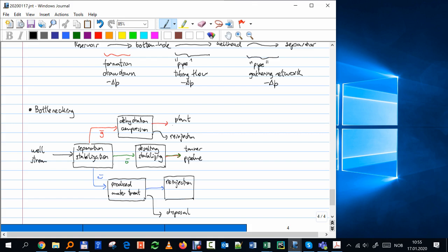Simply by separation, I mean it's like a multi-stage of separators. That's what you typically have. But after that, the crude still needs dehydration. It has significant amounts of water that you have to remove, and might have salt. You don't want corrosion because of water and salt. They can cause corrosion in the tanker, in the refinery, many things. And also stabilization, because that oil, if you put it in a tanker at atmospheric pressure, will still be able to liberate some gas. So you want to stabilize it so that it doesn't release that much gas.